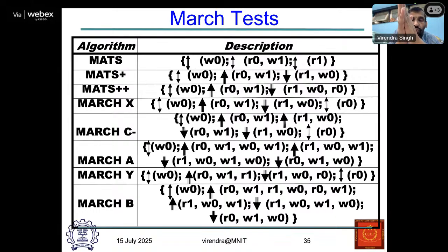We will continue with this one in the next class, and maybe then it has some relationship with the built-in self-test. So again we can revisit this one a bit later. The other tests are much simpler once you understand this March test: W0, then the three marches, M0, M1, M2, and why I need to follow some sequence.